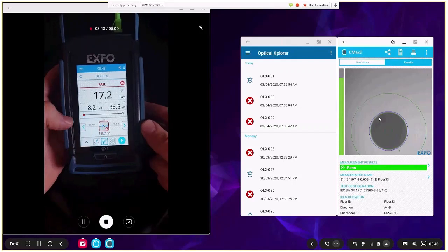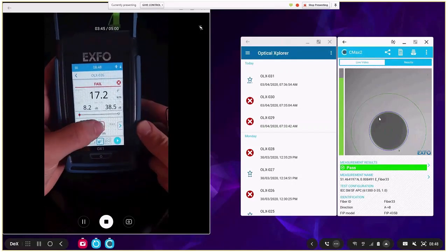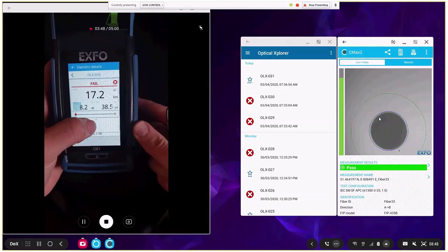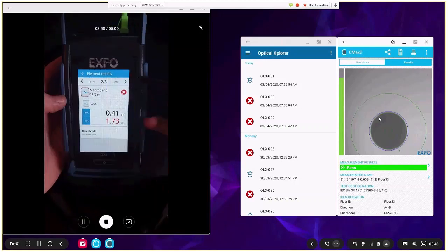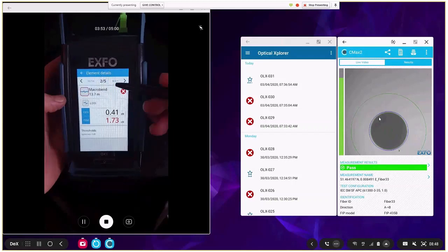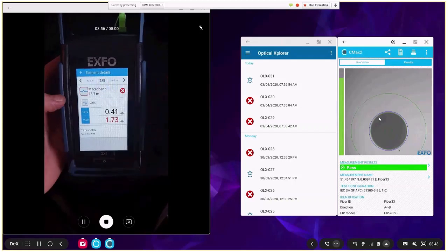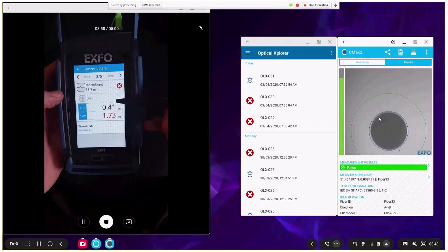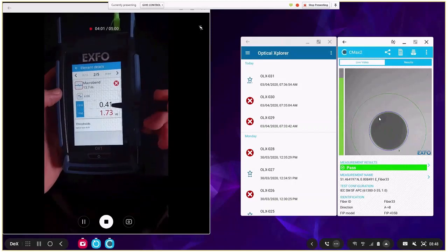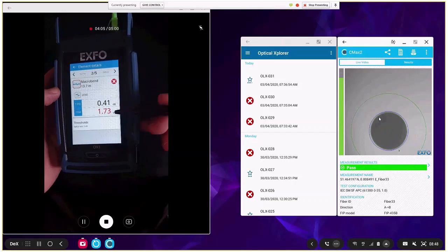As we've seen on the IOLM, using the Link Aware technology, we are able to detect these elements and correlate. As I explained before, the macro bend is detected when you have a different loss at 1310 and at 1550, at least 2 wavelengths to correlate.